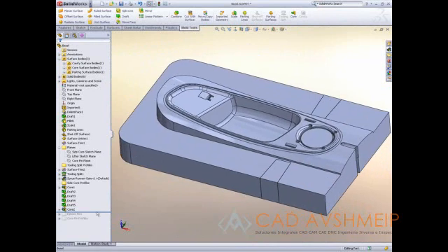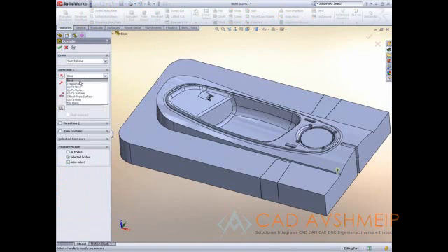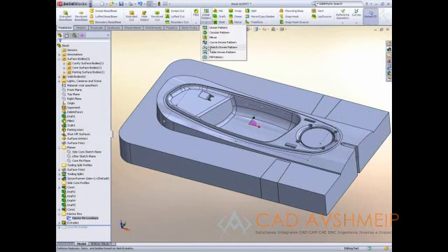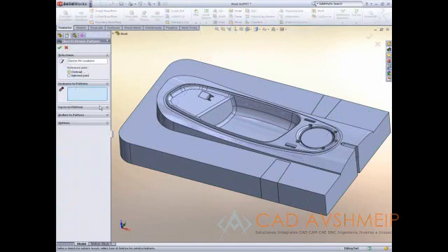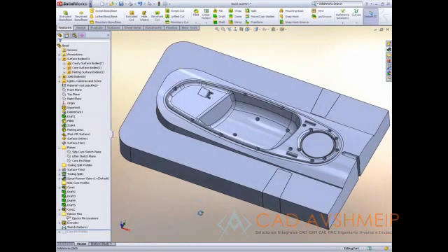At this time we may also want to consider the best way to eject this part and the best locations for our ejector pins. A simple hole can be created in the core side of the mold to locate the first ejector pin. Using a sketch with points to represent the centres of all the other pins is a quick and easy way to add these features. We'll create the pins in the mold base assembly later.